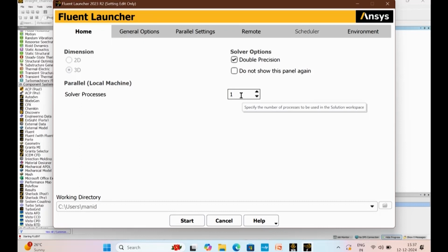And then the parallel option. You can see the number of processors, like the number of cores in your system. Normally the laptop contains 4 cores, so you can parallelize the Ansys code. But I think it is better to put less than 4 because it will take the entire space. So just put 1 less than the maximum limit. For now, for my case, I am taking 2.